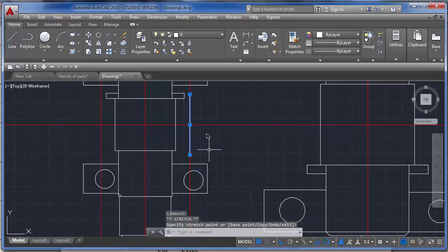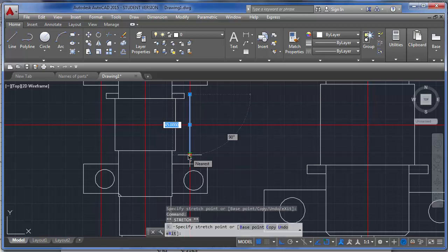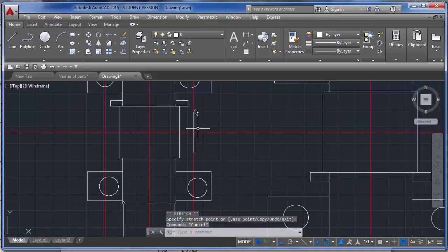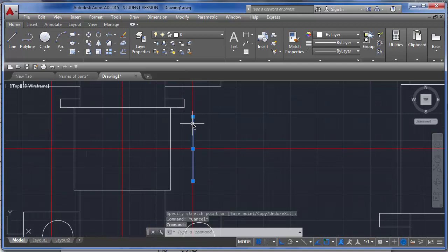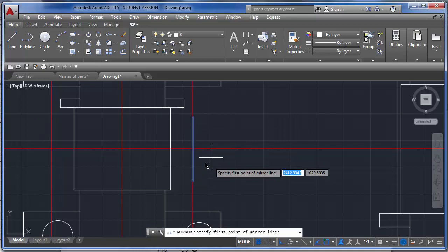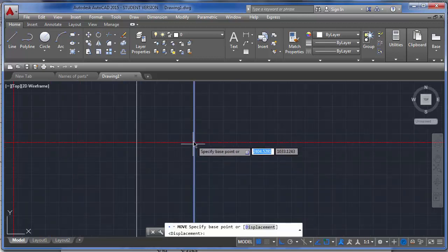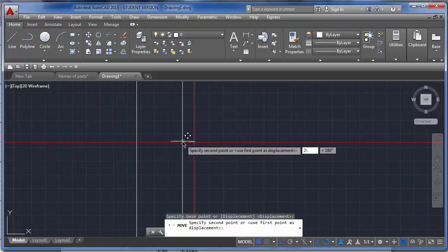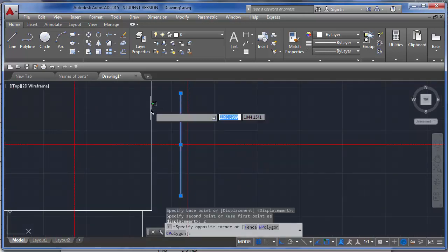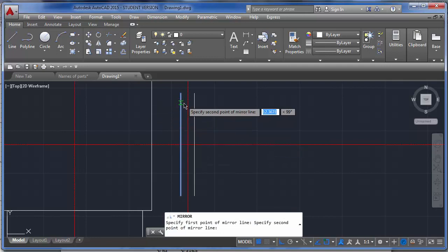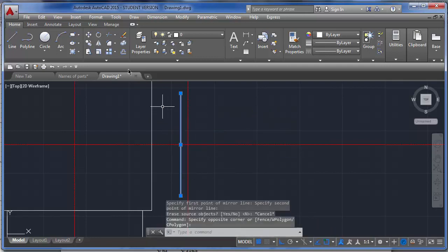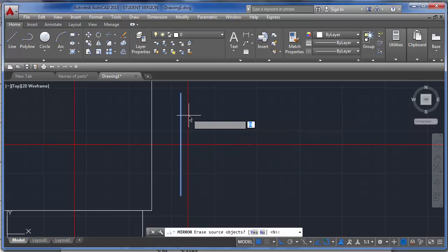Then push it down here. This is B2. Then actually this is your module line, and this line should be 3 millimeter. Oh, sorry, here your module is 2, right? So it should be 2 millimeter from this, from the left side. Okay. Select, move from here 2 millimeter. Okay, it should be mirrored about this point. Click, mirror about this point, enter.